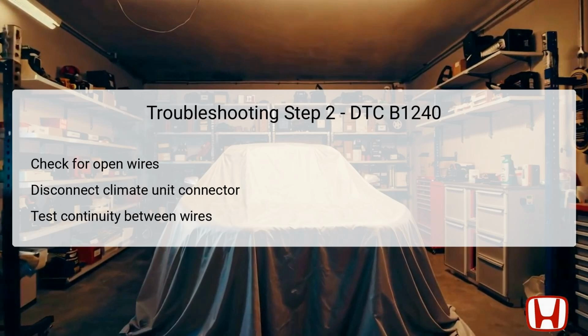If continuity exists, it indicates the wires are fine, allowing for progression to the next step. However, if no continuity is found, it signifies an open wire that must be repaired to ensure proper operation.